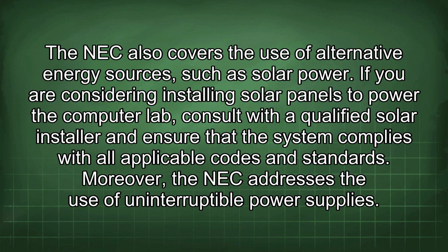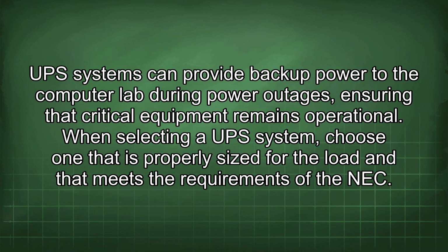Moreover, the NEC addresses the use of uninterruptible power supplies. UPS systems can provide backup power to the computer lab during power outages, ensuring that critical equipment remains operational. When selecting a UPS system, choose one that is properly sized for the load and that meets the requirements of the NEC.